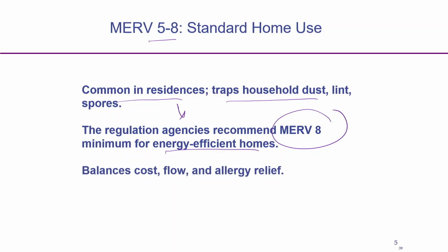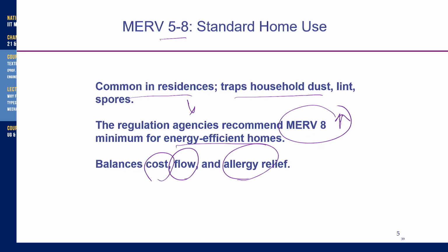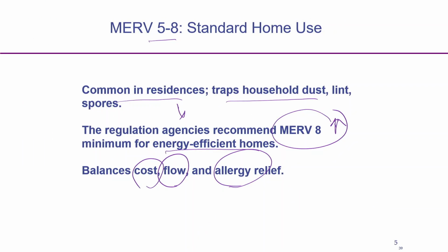It balances the cost, it will not increase due to the energy, optimum energy consumption. It will allow the flow rate also, and at the same time it will remove the allergic dust. So, MERV 8 is basically optimum for home application.